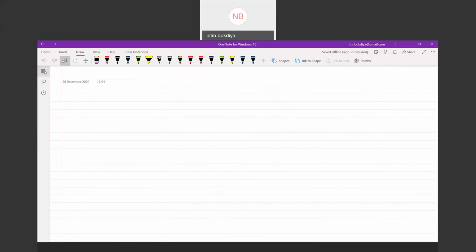Let's take one more problem based on the same concept. The concept of cascade amplifier is this. Beta is high for this circuit. This is given: in the AC equivalent circuit, the BJTs are biased in the active region and have identical parameters. Beta is very high. You are asked what the open circuit small signal voltage gain will be, and the circuit is given like this.